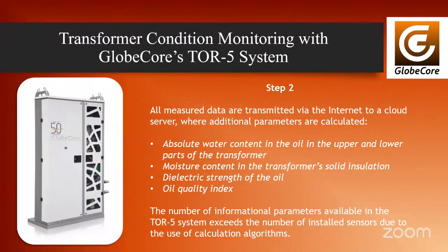All data from TOR5 sensors is sent safely to a cloud server. This is done through a fast router with special software. The router collects data from sensors using the Modbus RS485 protocol and then sends it through mobile networks, 2G, 3G, LTE, using HTTPS.